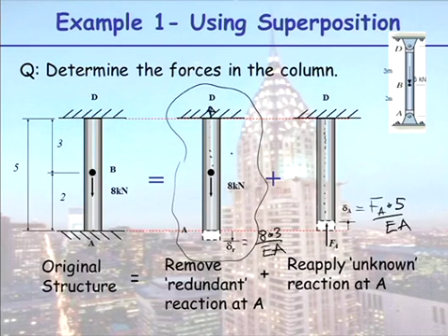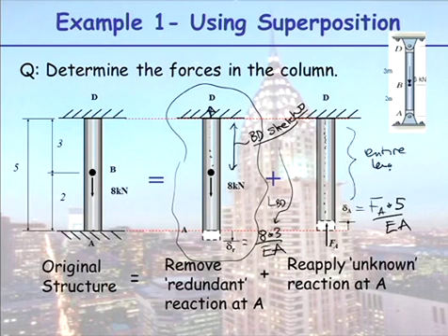I have an 8 force. It's causing only BD to stretch. So thus, when we use our formula, our length here is only the length of BD. When we apply our force back, it's the entire length now that squashes. So thus our length is 5 metres.